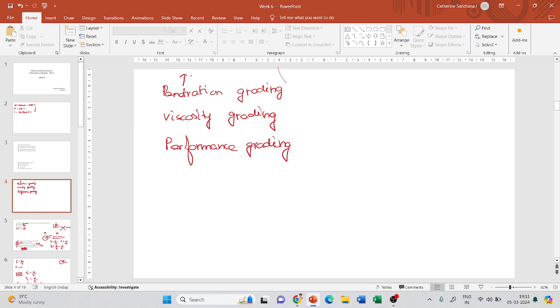And in that case, what do you think the temperature of testing would be? It would be the body temperature, the normal body temperature. But this is highly subjective, right? It varies from person to person, and it is not a standard measure. Chewing is a very naive way of identifying the consistency of bitumen.